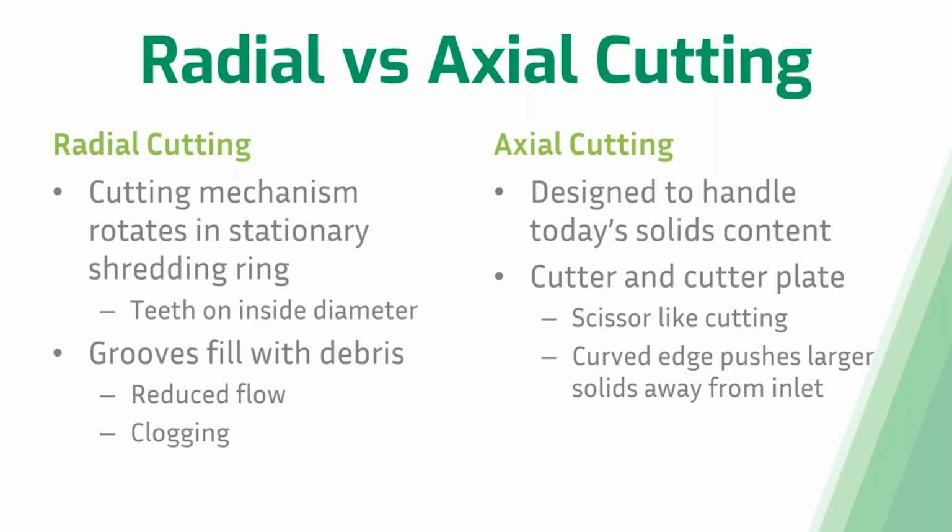Another thing to note is that with this design, typically there are curved edges on that cutter, which will push away those larger solids from the inlet when that pump turns off. So if that pump is in the middle of grinding something up, those curved edges can help push away those solids and prevent a clog from happening when that pump starts up again.